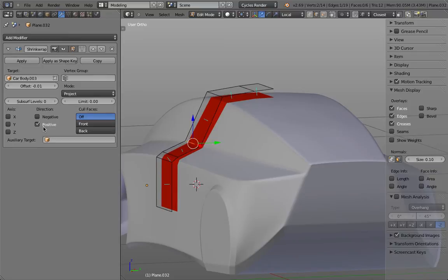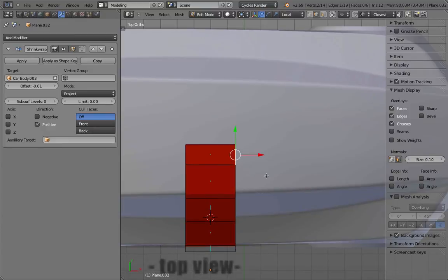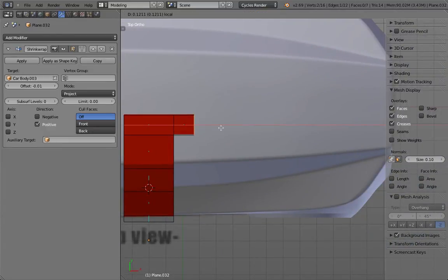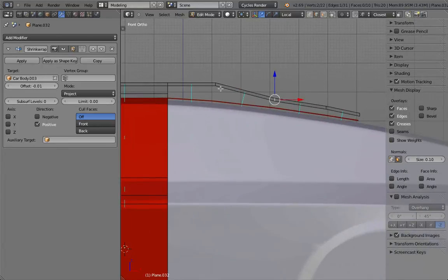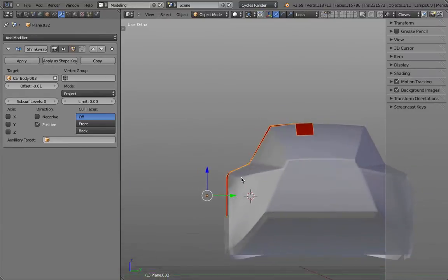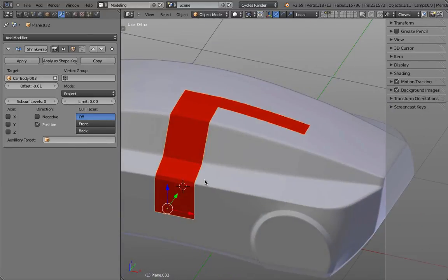And that is what you can use the direction function for. Basically, you model a surface around your object and try to, when you build it, follow the object's own surface or surface flow, and this way you can then make sure that actually everything follows nicely. So you see here, for example, I projected a little bit of geometry out and kind of like built a piece hovering on that surface.